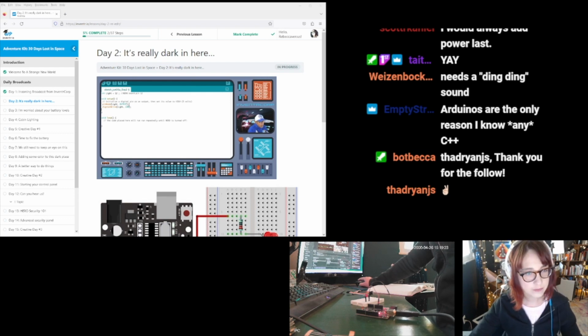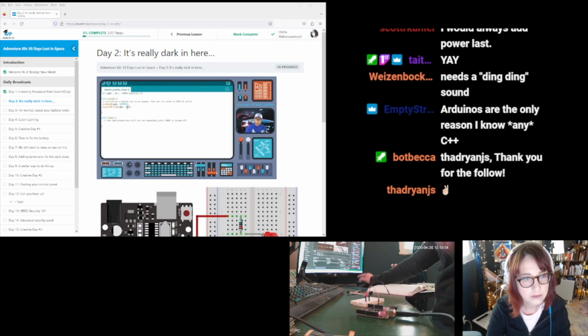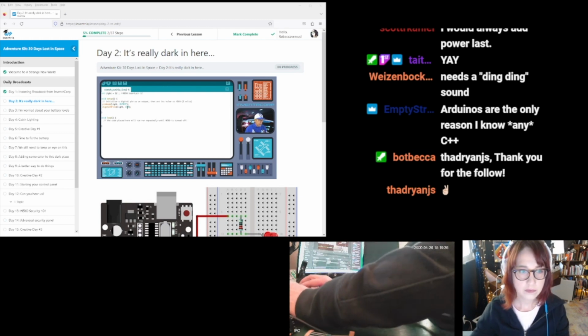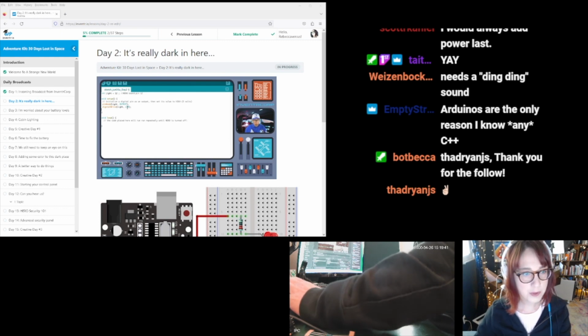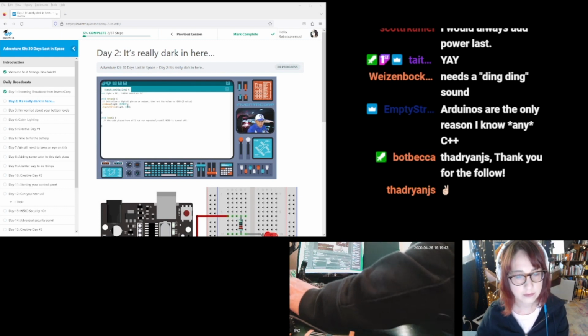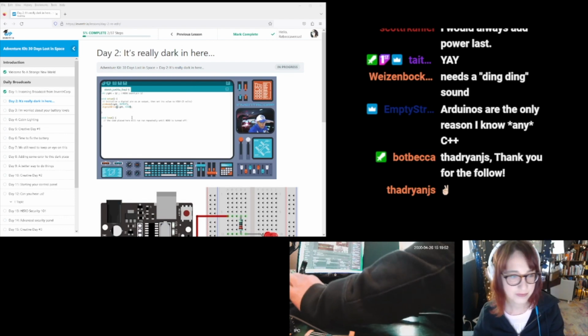Following the pin mode and its semicolon is another statement, digital write. Digital write now does something to that pin, in this case pin 12. And what it says is, set its voltage to low. Low is just another way of saying 0 volts. So when we see high, we're going to have 5 volts. And when we see low, we're going to have 0 volts. Now actually, since we'd like to turn the LED on, let's change from low to high. That way, when this is executed, pin 12 will now be at 5 volts, and that could be very useful to us.